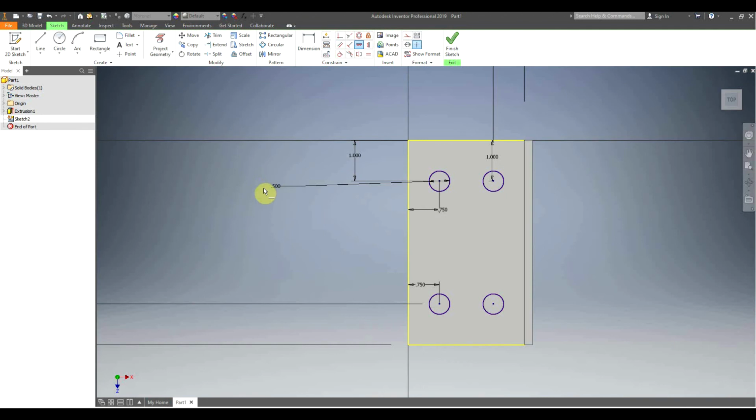And there we go. Now we can cut the holes, and when you finish a sketch, you want to make sure that your sketch is always blue. So your new sketch marks, you always want them to be blue, because that means they're fully constrained. If they're not constrained, they will look green like this, and you can take that and drag it. So see how I can drag that up? I can't drag it side to side because it's constrained in the vertical position.